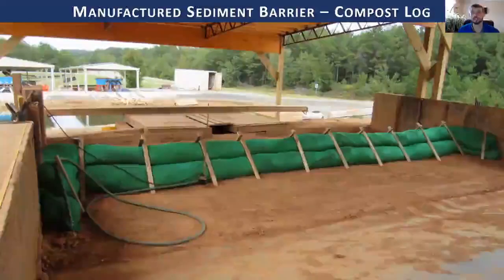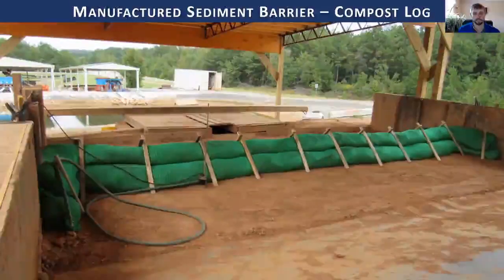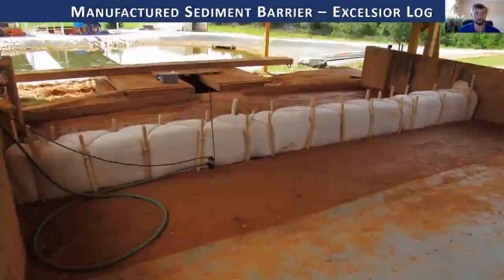We also looked at compost logs installed in a triangular fashion. So we have another tubular device, but instead of having straw, we have compost within these logs. And we actually did analysis on these as well. And then the last manufactured sediment barrier product that we looked at was the Excelsior log. So this is a square block that is filled with Excelsior fiber, and it is entrenched in the ground 2 inches and then held in place with stakes and rope.